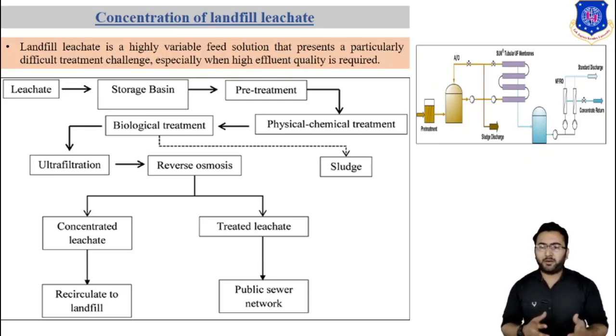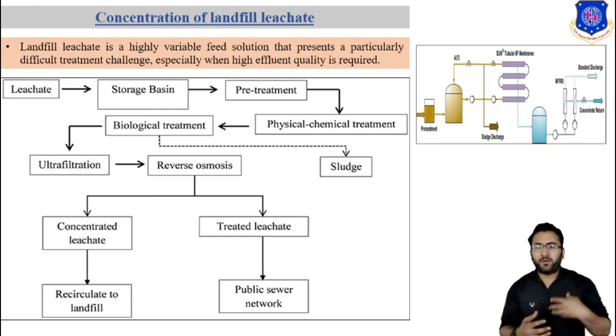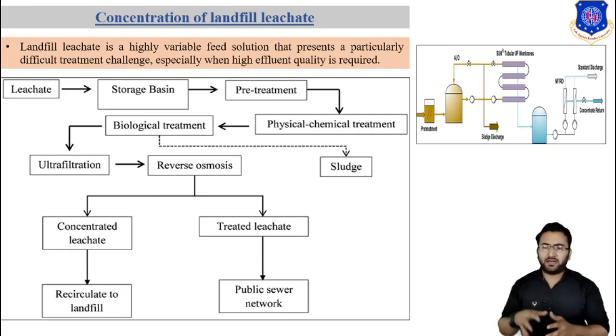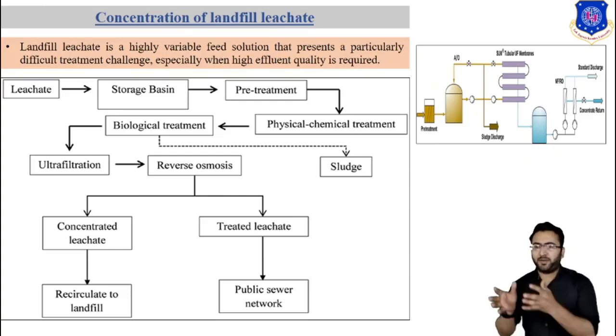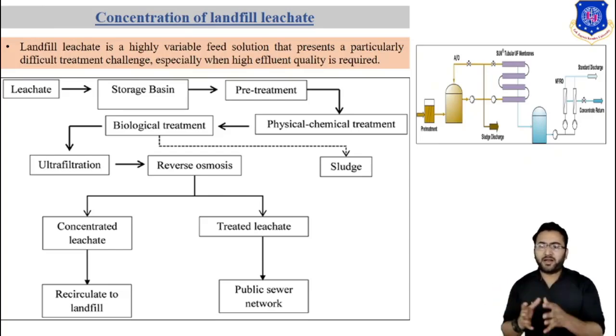Two commercially available treatment processes that are able to efficiently remove TDS from wastewater are mechanical evaporation, such as vapor compression, vertical tube falling film, horizontal tube spray film and forced circulation, and second, a membrane separation process. A comprehensive evaluation of vapor compression mechanical evaporation and reverse osmosis shows that reverse osmosis can be very effective in treating and concentrating landfill leachate.